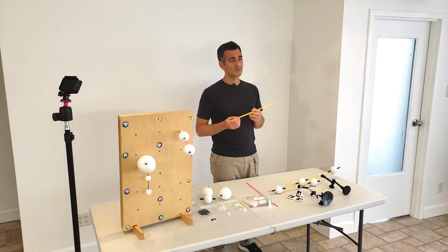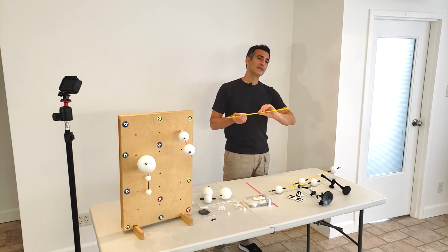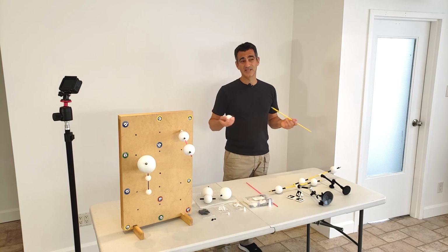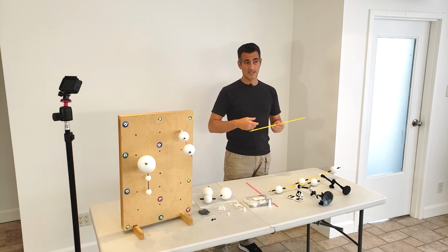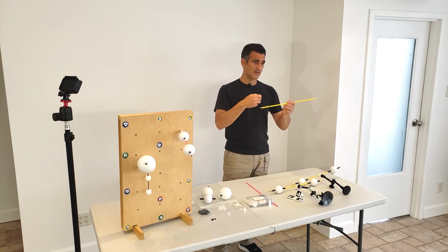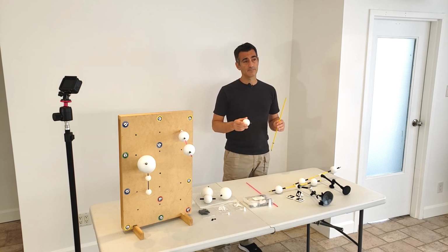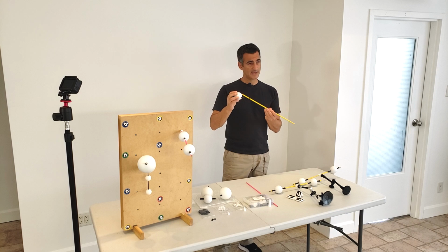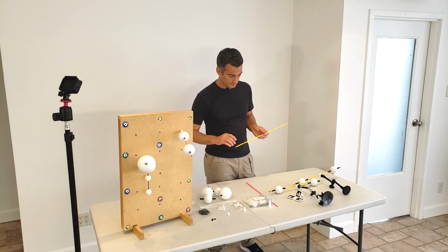Although there are some tools I've seen from different manufacturers that will try to connect to a rod, I've seen it be hit and miss. It's not the best way to work. Sometimes it goes off in nowhere land and you're still stuck trying to manually align the virtual trajectory. So using spheres, big bonus. You get good accuracy, you get a good centroid, and it gives you some additional range to work with.